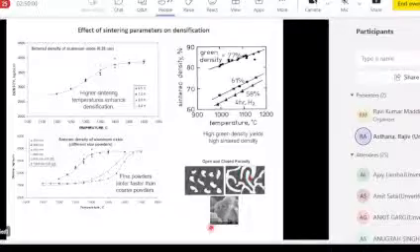The problem is closed porosity, that is, fully enclosed porosity cannot be eliminated. All you can do is basically forge or press the part to try to seal or minimize the closed porosity. You cannot fill closed pores with any liquid.